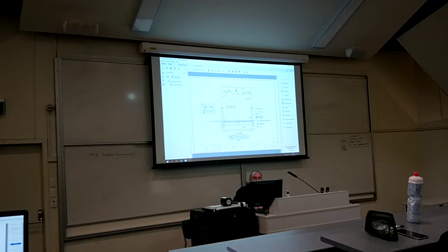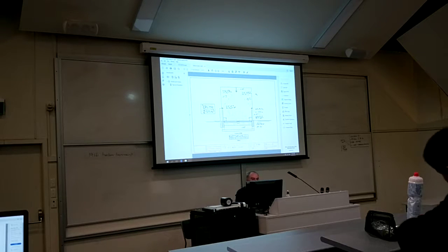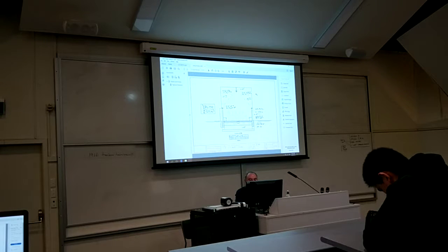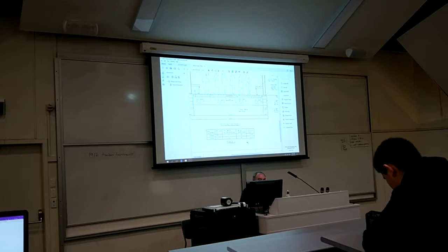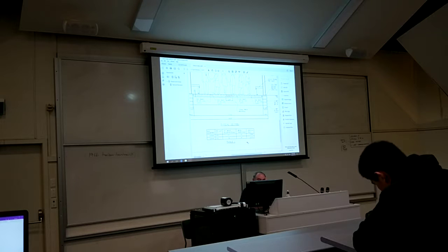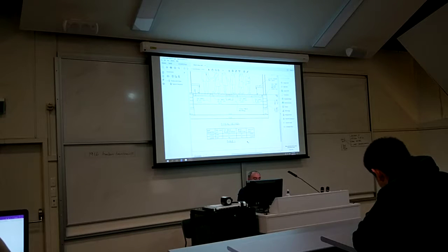Now, it looks easy, but it's not a case of just copying it. There's a lot of call-ups for the timber, which you'll learn about, steel, which you'll learn about, and the concrete call-up may be slightly different to the way I've called it up as well. Reinforcing ones. There's also a table down here, which a lot of students email me in week 1 going, I don't know what the bend radius is. What's the minimum lap? You haven't given it on the assignment brief. Okay? Diameter, minimum lap, 90-degree bend allowance, bend radius, and the mass. We will talk about all that in the lab, a little bit in the lecture, but you will understand that by the time your lab's finished this week.